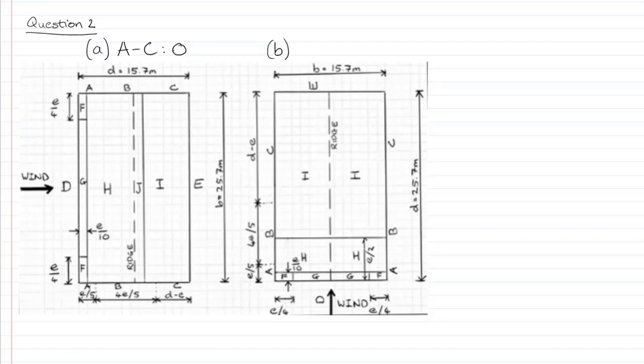And that is when theta equals 0 degrees according to the diagrams of the wind direction relative to where the roof pitch is, or the apex is. And so that is wind blowing from left to right, as the diagram shows. And it doesn't matter if theta is 0 or 180, if it blows from left to right or right to left, because the building is symmetrical, it doesn't matter. If this was a monopitch roof with a single slope, then theta equals 0 or 180 degrees has a big influence on your results.